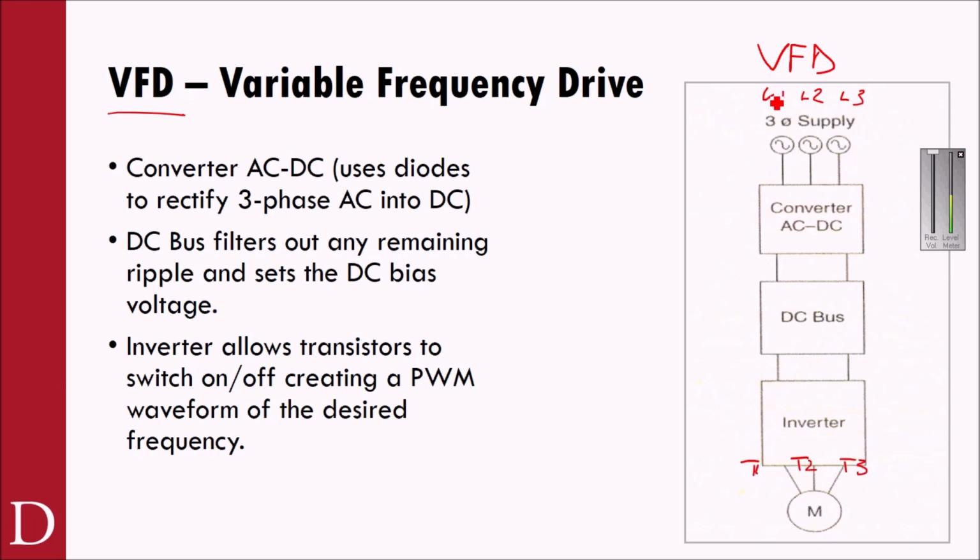There are VFDs. Here's another benefit of a VFD. You can get a single phase VFD. So let's say in your garage, you have 240 volts single phase, but you just bought a machine tool or something that needs three-phase power. You can actually use a single phase VFD to create three-phase power. It's one of the most common ways to bring three-phase into a residential garage is to hook up a drive. And actually in our lab, our VFDs are 240 single phase. But most VFDs you're going to find are three-phase in, three-phase out, just like a motor starter.